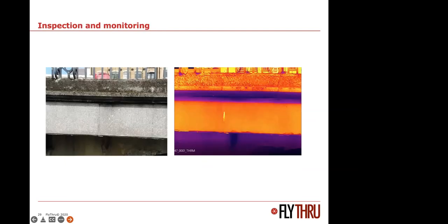And whilst examining it, we were asked to look for any thermal anomalies along the bridge top itself, which we found. And when we traced that directly upwards, there was a patch of tarmac that had been used to patch the footpath, which was basically leaking water through. And they were able to see in one single image and geolocate that. When they panned out, they could see exactly where it was in relation to the patch in the surface of the bridge itself, and do that very small minor repair to get rid of the water ingress.